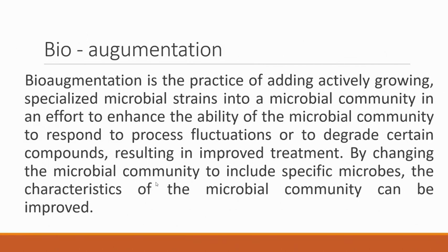Now let's look at bioaugmentation. Bioaugmentation is a practice of adding active growing specialized organism strains into a microbial community in an effort to enhance the ability of the microbial community to respond to process fluctuation or to degrade certain compounds, resulting in improved treatment.